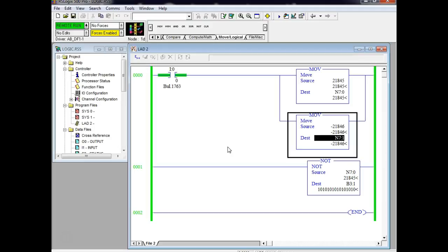So if I was going to do a NAND, I would have to do it with two rungs. Right? You understand that? How many outputs can we have per line? One. Or per line, not per rung. How many outputs can we have per rung? That's in parallel. So in motor control, there's no such thing as series parallel circuits. They're all one.